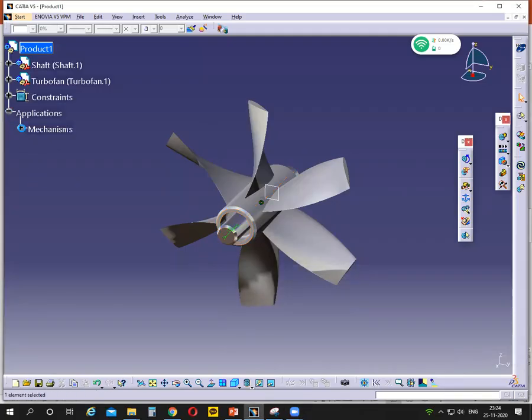So the revolute joint is finished, right? Here DOF is 1, okay? So that means we cannot simulate that one, restricted motion. This revolute joint only consists of one mechanism, one joint, the revolute joint. That is enough to simulate this motion, okay.